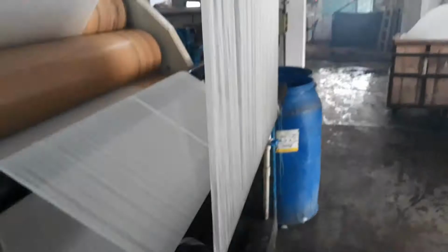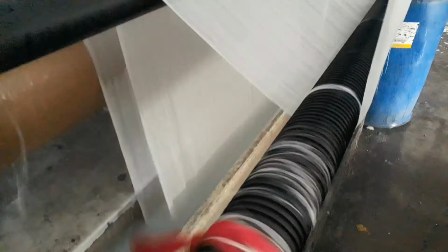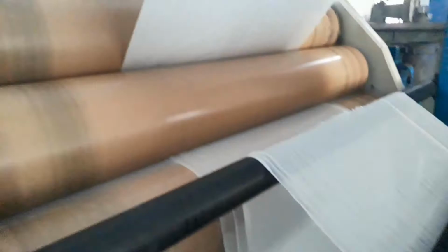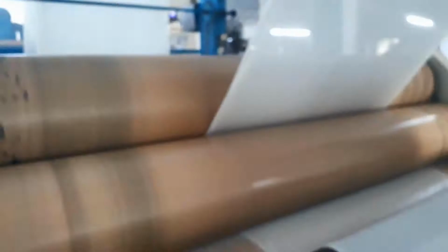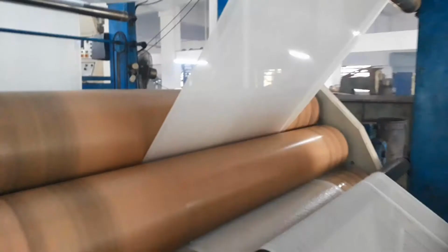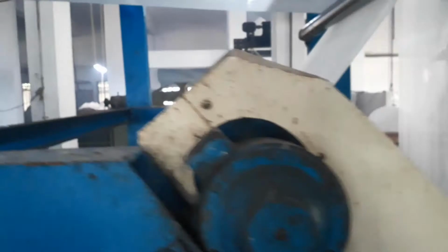But here I think it is heat setting, and heat setting is done by passing the fabric through water, which may be on acidic side, and then it is squeezed by passing through the nips of this padding mangle, and then it enters the main chambers, heating chambers of the stentor. Before that, it passes through the straightening device and tension device.